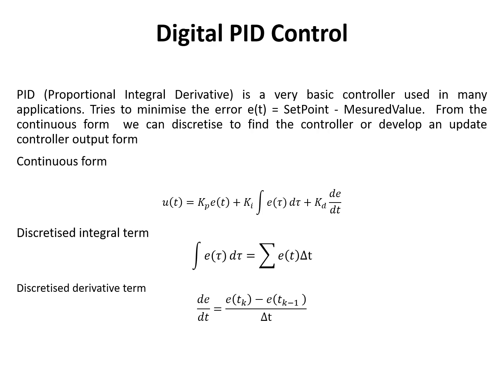So the proportional integral derivative, or PID controller, starts off by firstly determining an error term. Now the error term is nothing but the difference between a set point or our desired output. So if we're just doing some pressure vessel controller where we want to set the pressure inside a vessel, then we will have the set point as, say, 10 bar, that's the internal pressure we want. Or if you're doing a speed controller, cruise controller, we might want to say we want to drive at 120 kilometers an hour and therefore set the desired output to this value.